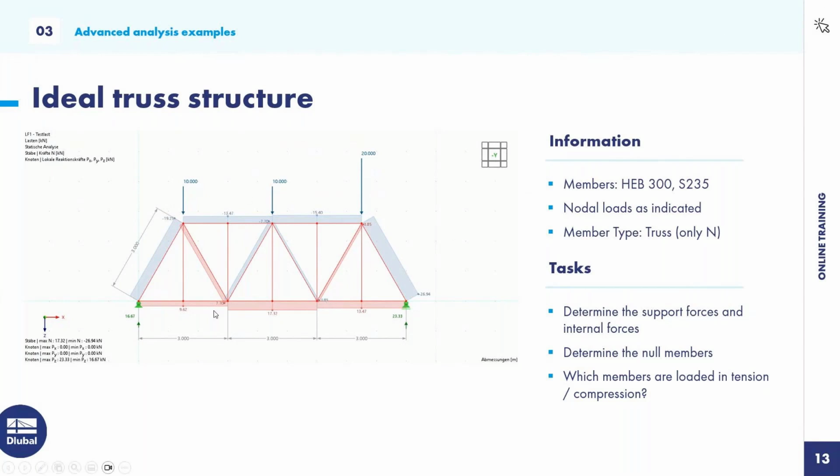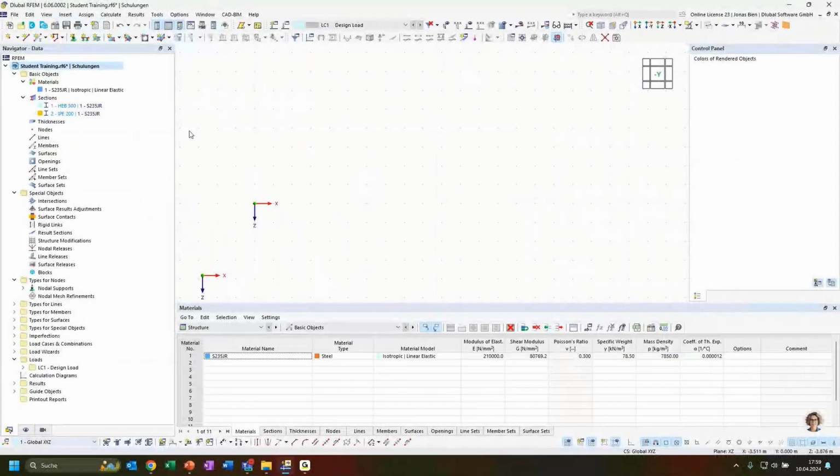All right. So just as a quick note, this truss is made of multiple triangles, and all the triangles have the same length of 3 meters, which means that they also have the same opening angle. So if we, in the first place, neglect those vertical members that divide those triangles, we can model the truss structure in cells of triangles that have the same opening angle and the same member length, and we will do that now. All right.